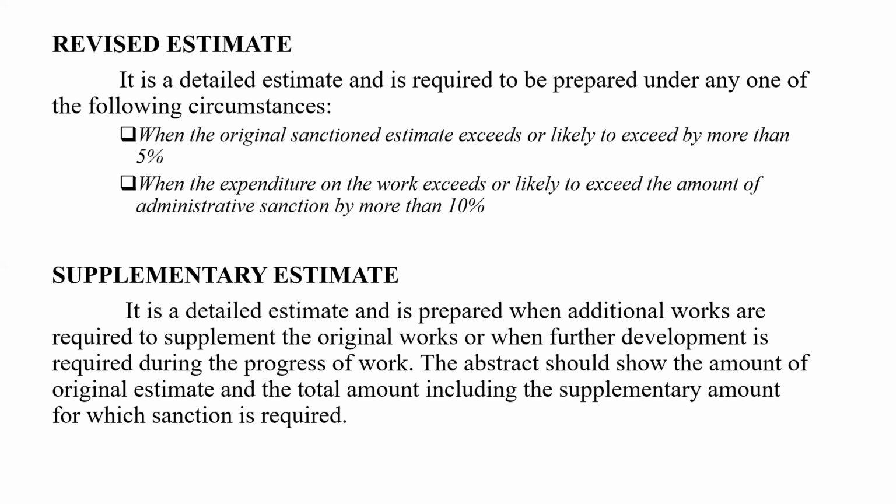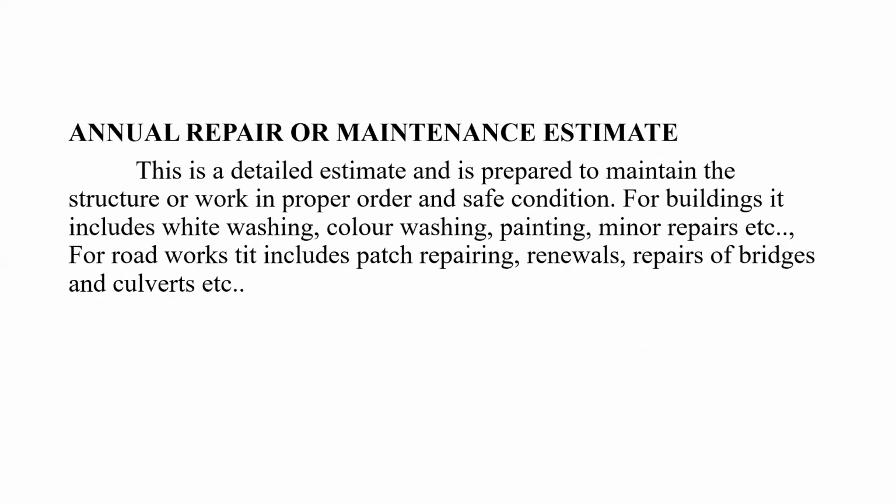This is a detailed estimate and is prepared when additional works are required to supplement the original works, or when further development is required during the progress of work. This is a fresh detailed estimate of the additional works in addition to the original estimate. The abstract should show the amount of the original estimate and the total amount, including the supplementary amount for which sanction is required.